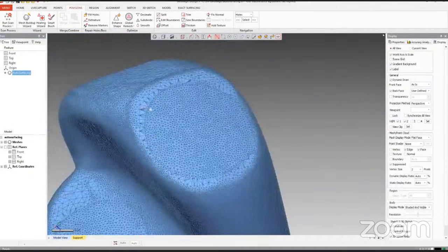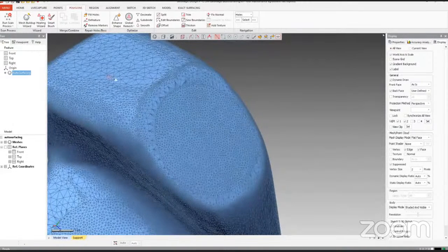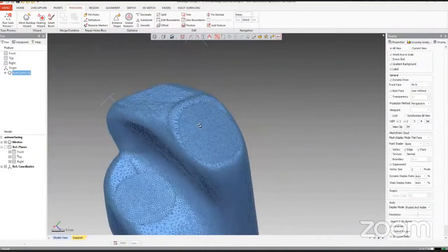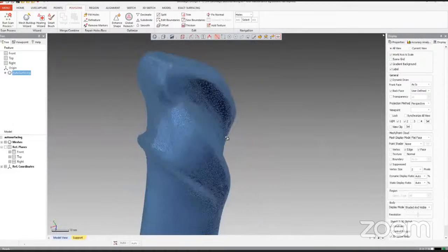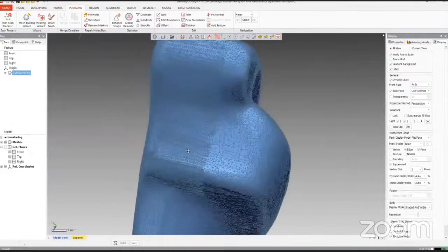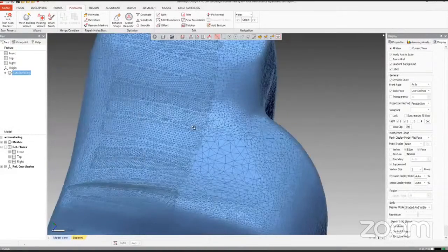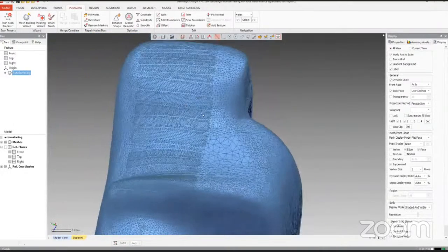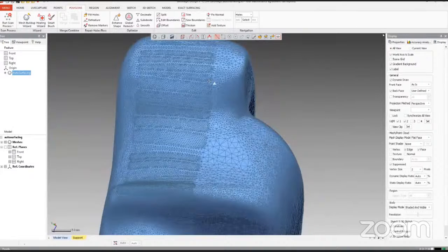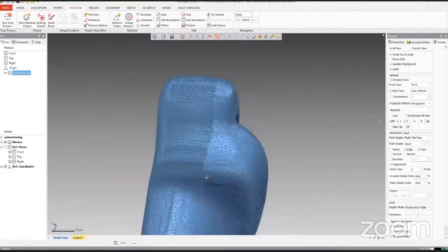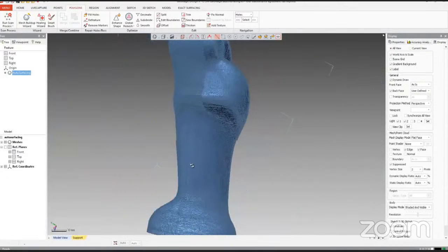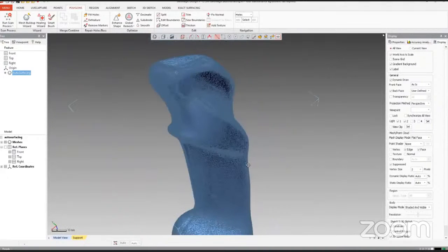So for that, we have features in the polygon tab. It's called global remesh. We can use these global remesh features on the mesh data and get the result, which is a more constant and similar pattern, like the sizes of the triangles are constant throughout. We can also see at the back that we just filled it up. There are small triangles there. Such information really affects the designing capabilities of the CAD designer.